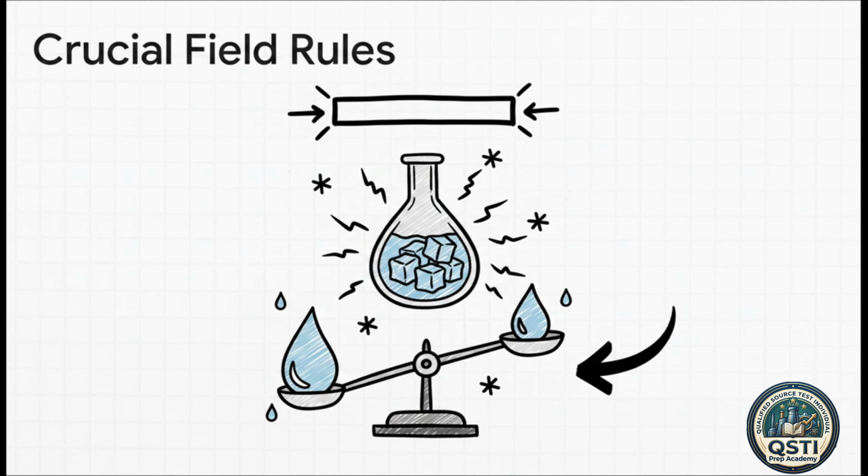Speaking of vital, for your final takeaways, you need to burn these 3 rules into your brain for test day. First, during your run, you must keep your sampling rate within 10% of a constant rate. Second, you gotta add ice to cool that silica gel outlet well below 20 degrees Celsius, which is 68 degrees Fahrenheit. And finally, if you are dealing with a saturated gas stream, or maybe one with water droplets, you actually have to do 2 calculations, one with a psychrometric chart and one with your impinger analysis. The golden rule here, you always use the lower moisture value of the 2.